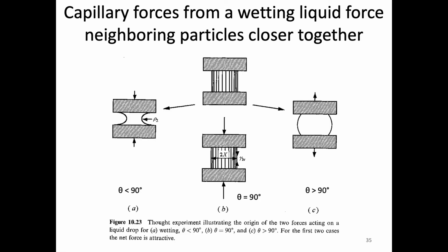And what that does is there's only so much volume of liquid, and so that creates a force causing the solid plates to move up for the bottom one and down for the top one, and that pushes them closer together, and that creates a situation where there's a force actively bringing the particles closer together. And that's the capillary force. This is the capillary force you may have seen inside of a glass tube. And this is bringing these particles closer together. So for our liquid phase sintering, this is helping us rearrange so that the particles are closer together.